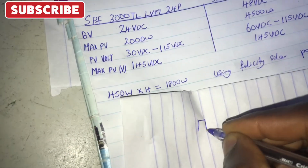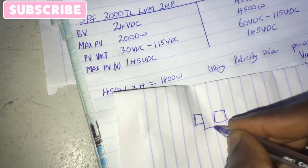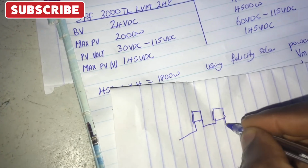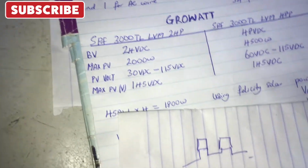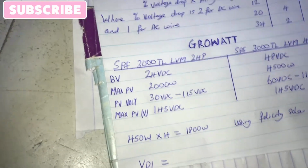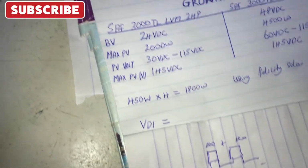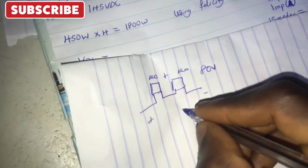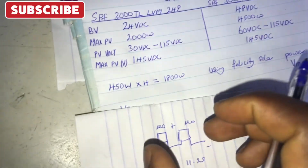2 series, that's connecting 2 panels in series like this. That's positive to negative, leaving you with one big giant positive and one big giant negative. So doing this connection, the voltage is going to add, which is 40 plus 40, giving us 80, while the amperage remains the same, which is 11.25. This is just 2 panels.